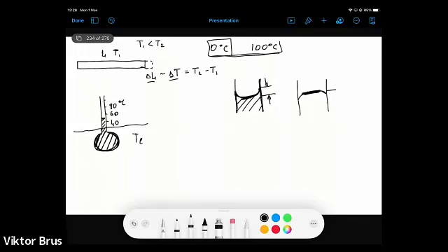The thing is that when we increase temperature, then there is a small part of mercury which stands in this tube at a level higher than our liquid. Means that small part of mercury will not be at the same temperature as the liquid where we want to measure temperature. And that will result in some error in measuring temperature accurately.